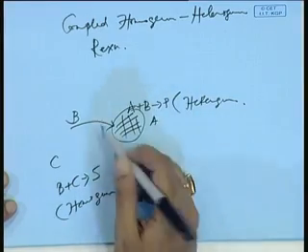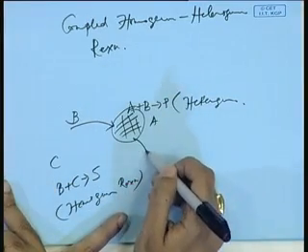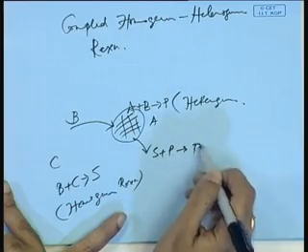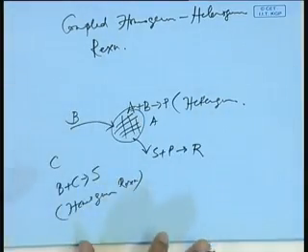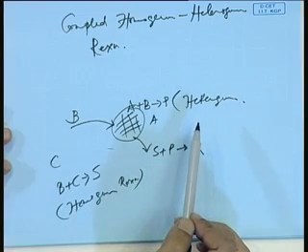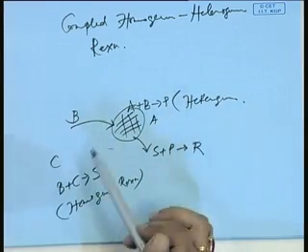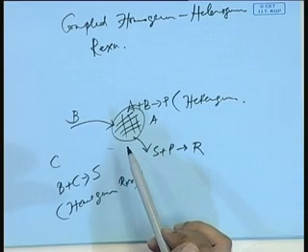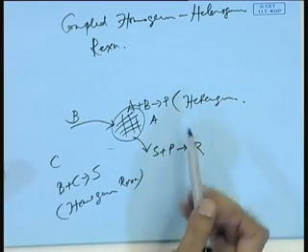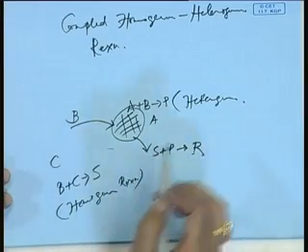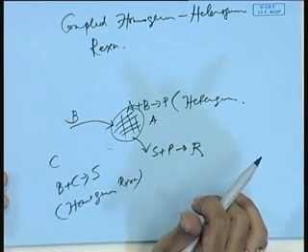For example, you can have this, and then you can have a reaction on the surface of this, S plus P giving R. So this is a whole network of reactions, and typically in real life most of the reactions belong to this category, where there will be some reactions which are homogeneous. If you work in industry with chemical reactions in catalyst beds and stuff like that, that is always something that will happen. Why? Because maybe your heterogeneous reactions are the ones that are desirable, the ones that you want, but there will always be side reactions that will happen in the bulk. So this is very likely. This is the fourth kind of reaction, the coupled homogeneous heterogeneous reaction.